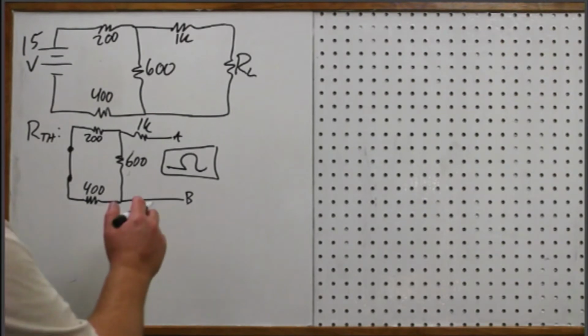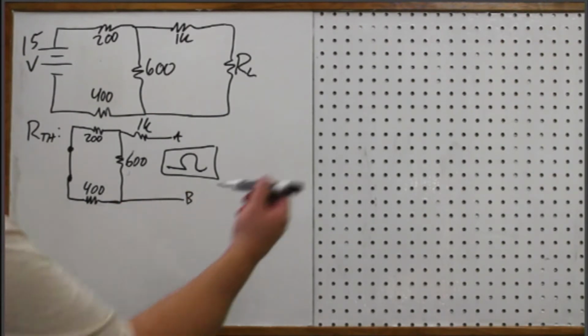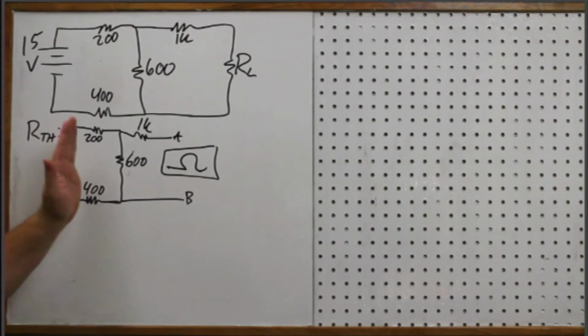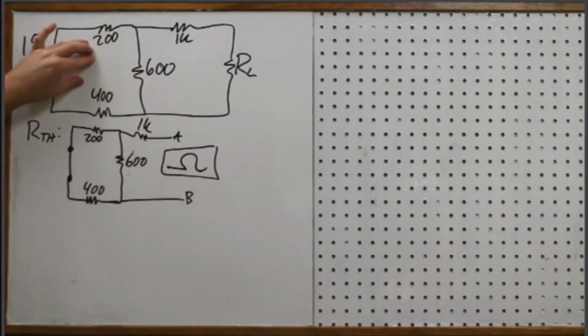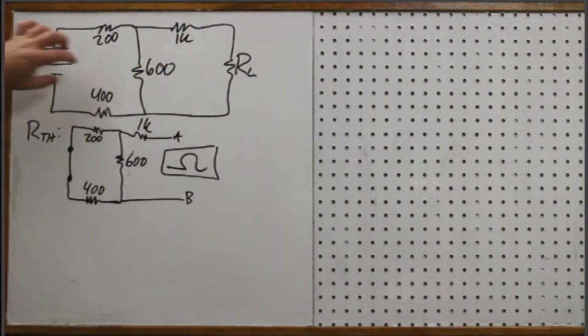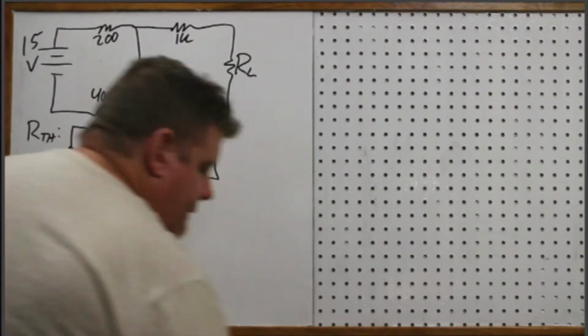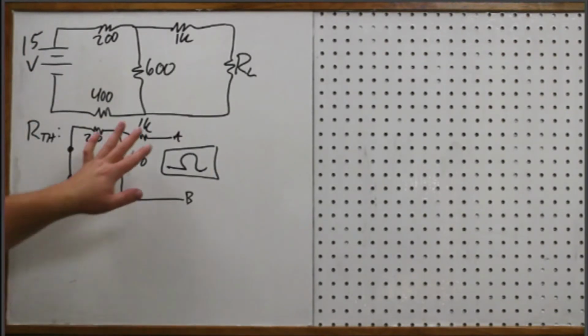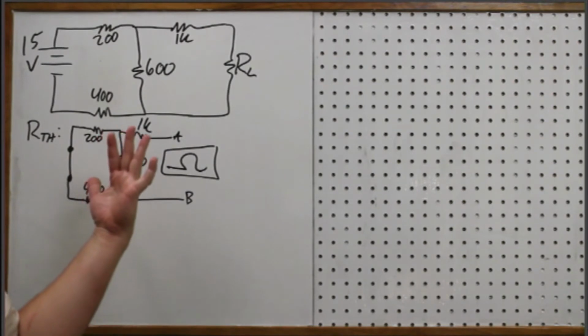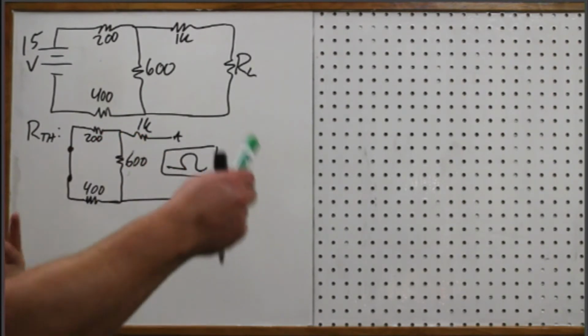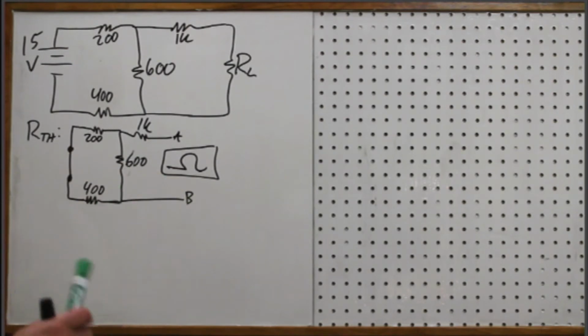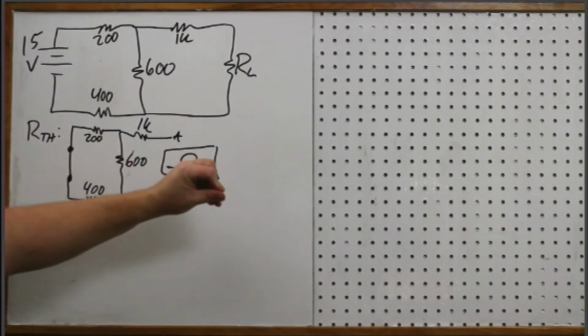All right. So it looks a little different because this time we're going to start farthest away from the meter, which would be over here on the left, and work ourselves right. Normally in this format, we work ourselves back to the source. In this case, we're going to work the opposite way just because that's where the load resistor is. Okay? So I'm not going to do anything different. If you need to, you can flip this 180 degrees just so the meter's on the left-hand side, and then you will be working right to left. But you're still working farthest away back to the meter.